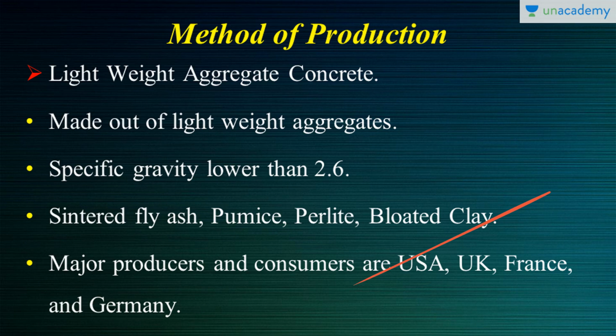There is also a chance of shrinkage, but shrinkage won't matter much because capillary action won't happen much because of the wider cracks inside. These are some of the precautionary points we need to keep in mind while working with lightweight aggregate concrete, and appropriate methods have to be adopted to counter all these effects.